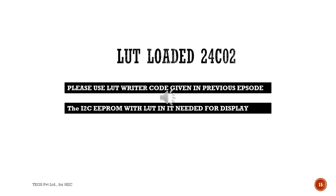The LUT loaded in the 24C02 EEPROM is needed to proceed further. Please use the LUT writer C++ code given in the previous episode. The I2C EEPROM with the LUT in it is needed for testing the display.